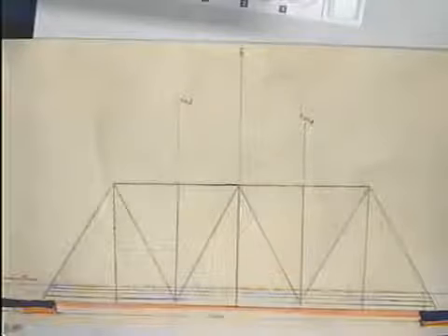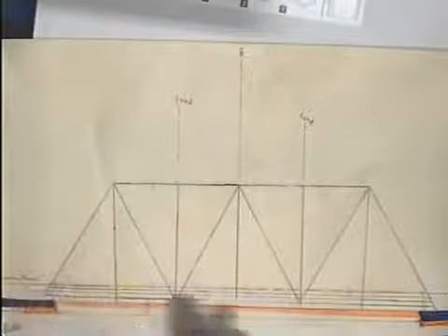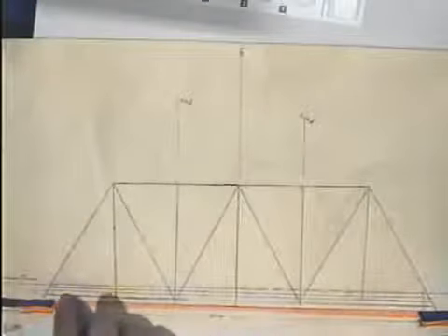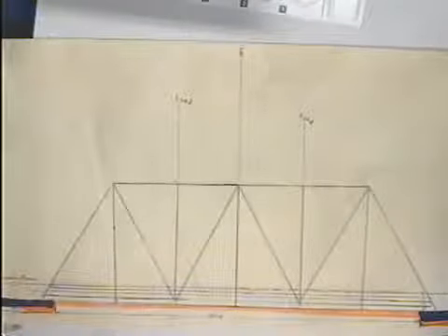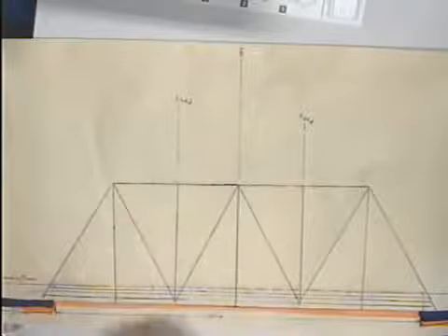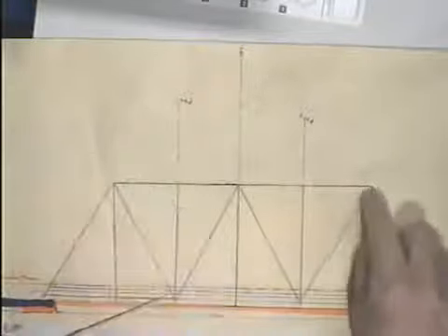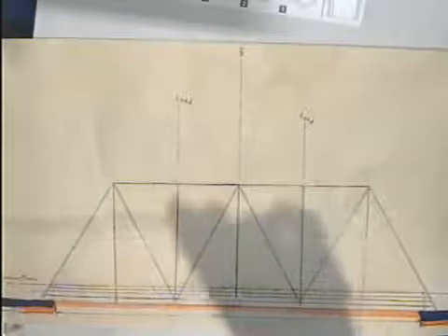If we go back to the drawing that we have over here, which part is under extension? Almost all these bridges, the bottom part here is going to be under tension. Okay, so we really don't need it that strong. I happen to make it that strong for other reasons. But where do I have to brace it to take care of the compression? Up here at the top. I had to brace that so the compression of this would not bend it.